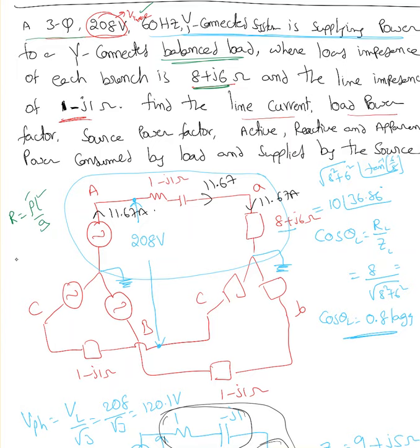And the conductor is hanging in the air, and the earth is going to act as another wire. One plate is going to be positively charged, so it's going to act like a plate. The other is going to act like a negative plate, so there is a capacitance effect. That's the reason it has some capacitive reactance. In most cases that capacitive reactance is smaller compared to the inductive reactance, because every current carrying conductor will have some inductance effect. So definitely it will have some inductive reactance. For this example, I chose this number, 1 minus J1.